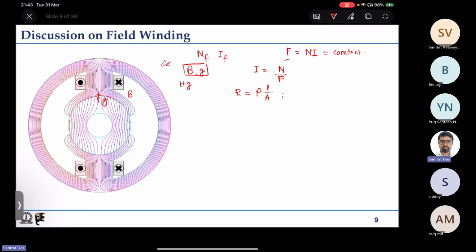So first thing, L depends on the number of turns that we have, so L is proportional to N. And the cross sectional area, A in this case, where I am writing as capital A. So what is A? A is current by current density. So J is the current density. So A, the cross sectional area of each turn, that is I by J. So that is the next thing.